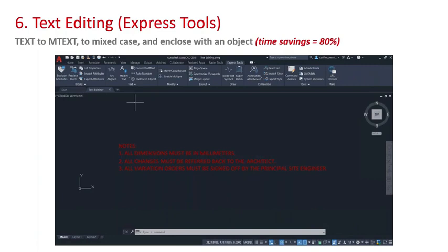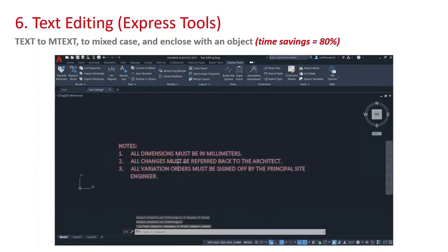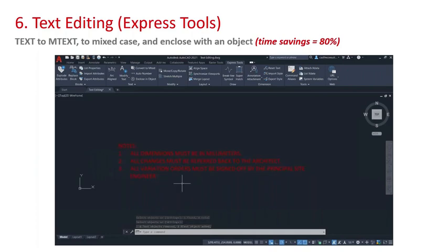I'm going to hop over to the text panel in the middle there. There you go, there's text, and I want to convert to mText. And all I've got to do here is select the text I want to convert. So I just select all of them. Each one, just a little click on each bit of text and press enter. That's it. And you'll notice, can you see how that changes? You'll notice that obviously it changes based on the multi-line text, and a bit of text even drops down. That's all one piece of text now.